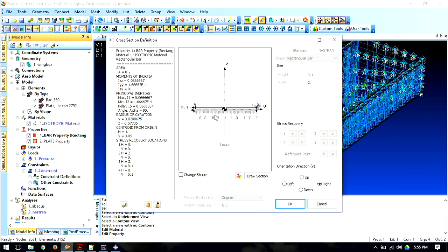So that beam is taking the bending moment? It takes a little bit of the bending moment. The way you figure that out is you look at the running loads in the skin and you compare that to the axial loads in this beam element. And typically, you can make this take the bending loads if you make it thick enough and you make the skin thin enough. It all comes down to stiffnesses of the wing cross section. Is the spar cap going to be stiffer than the skin? So it's up to you. So you can play around with that.